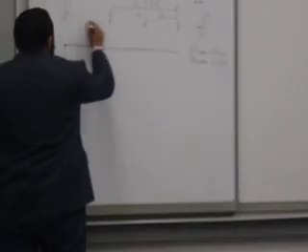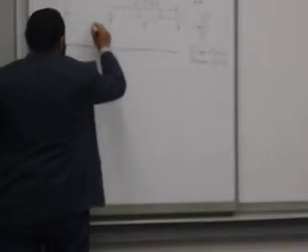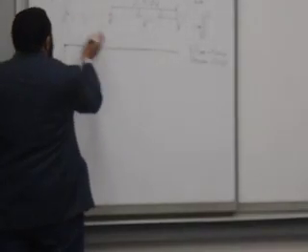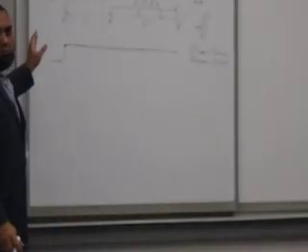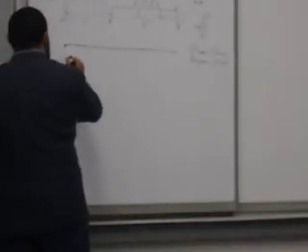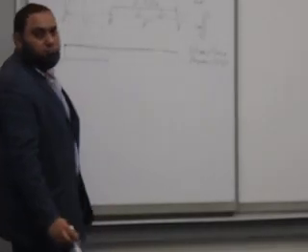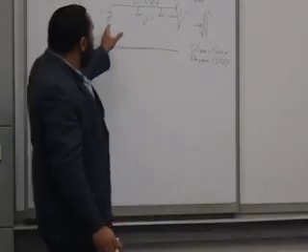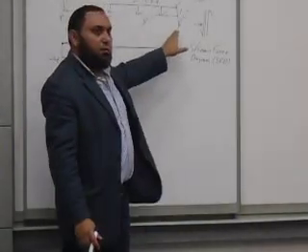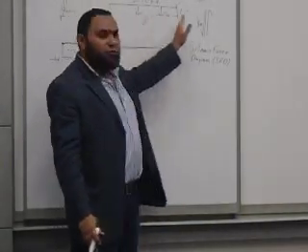If I take a cut anywhere between A and B, here, here, will I see anything different than that force? No. So the force is constant until I meet point B. Do you agree that when moving from B to C, the more I move towards C, the more force I'm receiving?